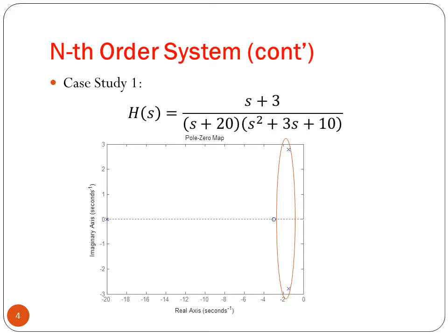In fact, we have a system of order 3. We have one pole, 3 zeros. When doing the PZ map of the poles and zeros, we found that we have two complex conjugate poles, a real pole and one real zero, all with negative real parts, thus the system is stable. So we'll approximate this function by the complex conjugate pair of poles. This approximation must be good. The remaining pole is far from the complex conjugate poles, and the zero is near this pair of poles.